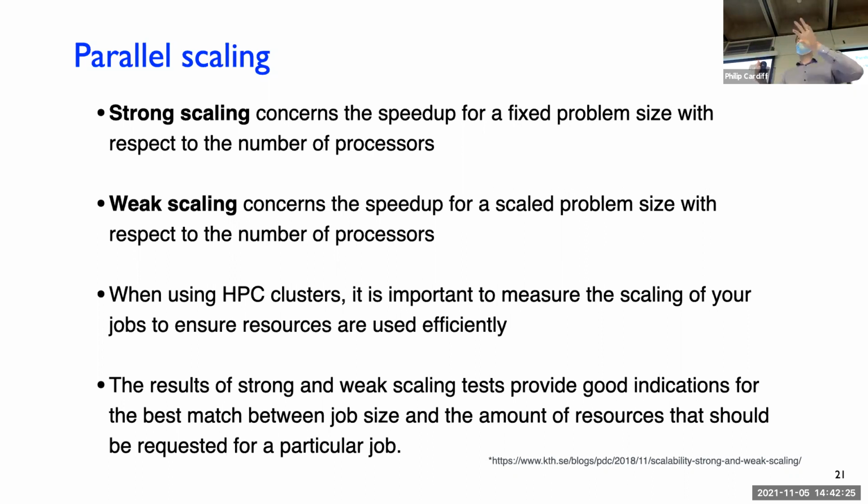So the number of cells per core is always the same, but it's a measure of the communication efficiency. If you're really getting into high performance computing, you would do both of those studies to check the efficiency of an algorithm. But for you, from a practical perspective, just run your job on a few different numbers of cores the first time you run it and get a feeling for whether it's faster or slower as you change the number of cores.